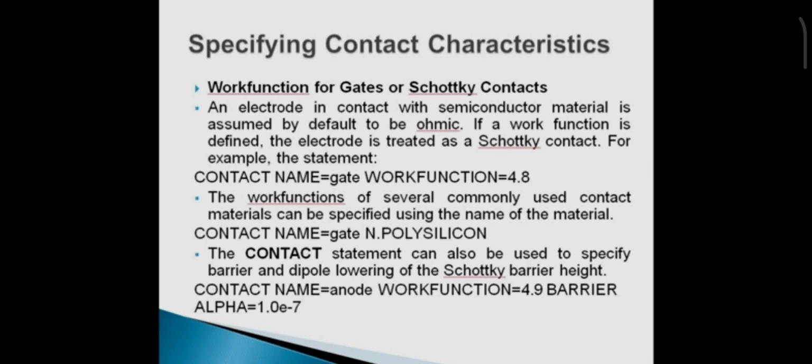One most important thing: when a Schottky barrier is defined at a contact, we recommend that a fine mesh is present at the contact in the Y direction. This allows the Schottky depletion region to be accurately modeled. Next slide please.